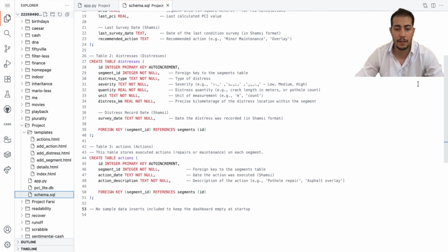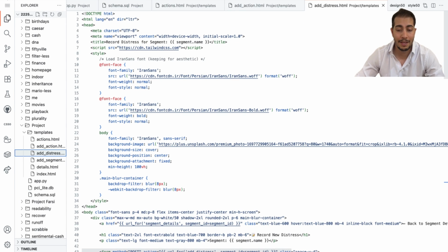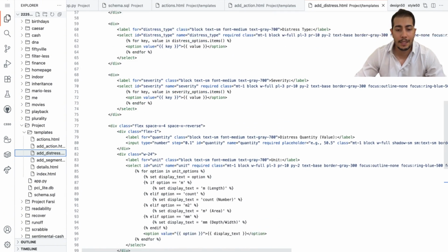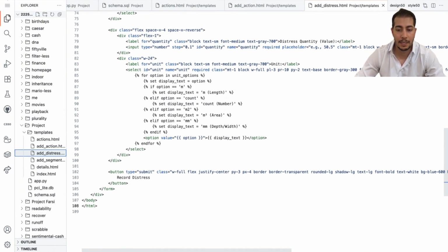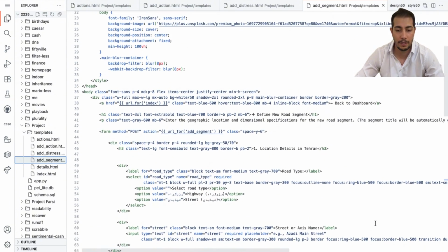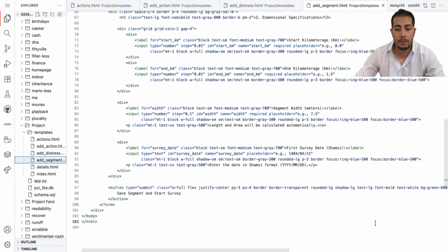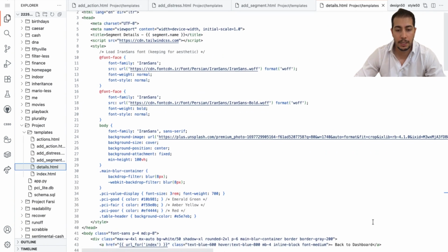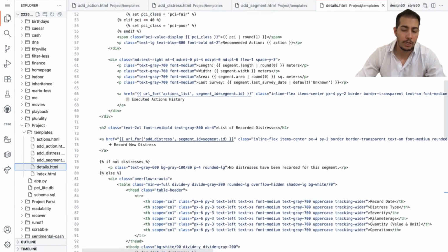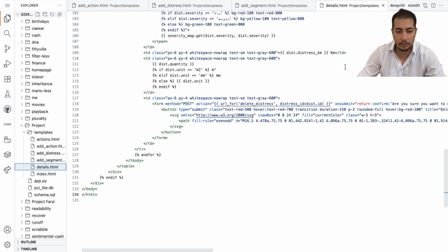Firstly, I achieve this by calculating the road segment's area, I mean length times width, and then calculating distress density. This density value is multiplied by a highly scaled weight. That's a necessary step to ensure even small amounts of high severity distress correctly impact the final PCI score, which ranges from 0 to 100.